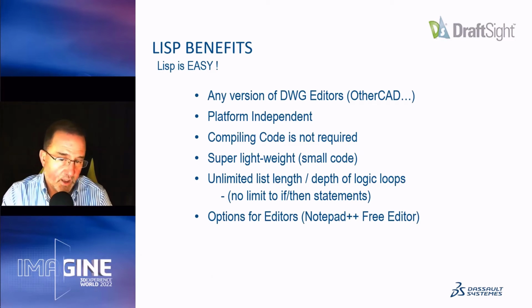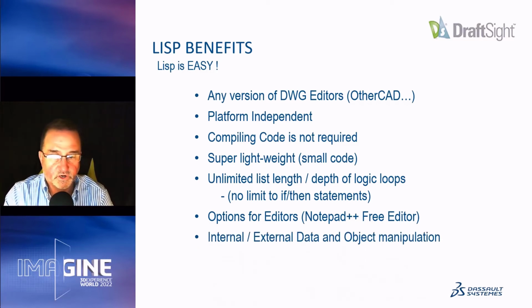Now, I prefer to use Notepad++. It's a free editor. It works really well. But you've got multiple options for editors. You can use Notepad if you want. Also, any of those other editors that are out there, they just have to be able to cleanly edit the Lisp routine file and keep it as strictly ASCII code. I'll show you what I mean by that here in a minute. Also, with Lisp, I can manipulate things inside of a drawing, and also I can manipulate data outside of the drawing. I'm not just limited to working inside of the drawing.